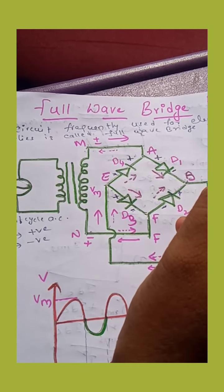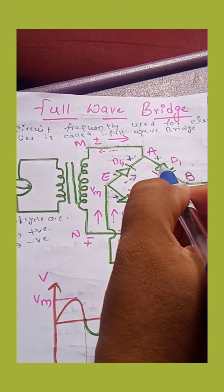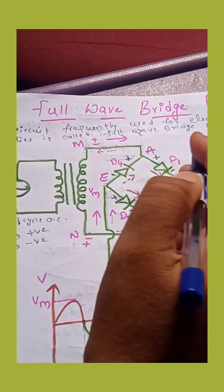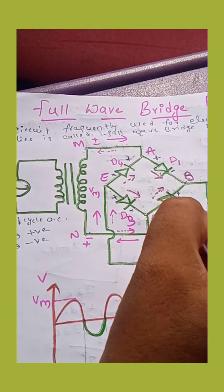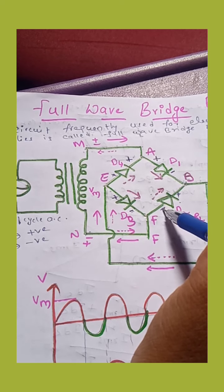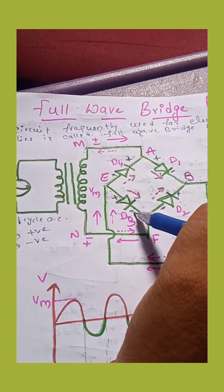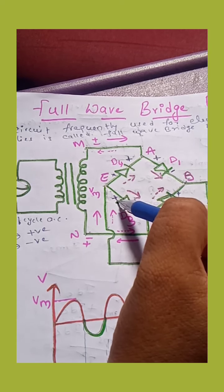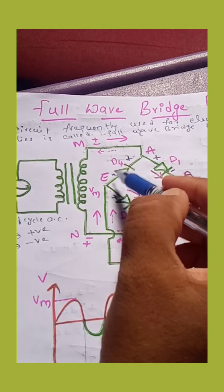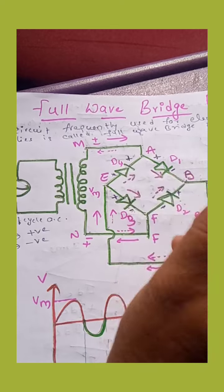Now see the diagram. If we take the D1 diode, the positive terminal is at P of the junction diode, so D1 is forward biased. Now if we take D2, to P a negative terminal is there, so D2 is reverse biased. For D3, again for P we got a positive terminal, so D3 is forward biased, and for the D4 diode again P has a negative terminal, so it is reverse biased.